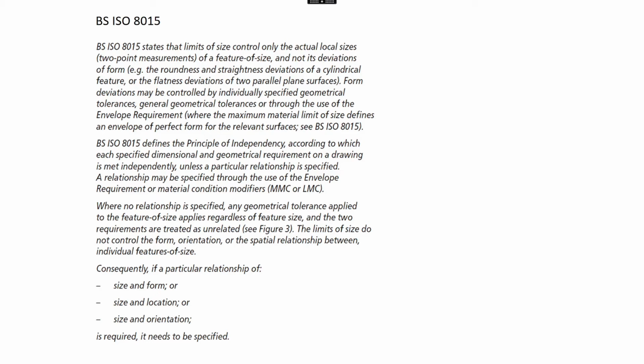So this is actually used now more instead of the triangle with the I in it. So you say it's drawn in accordance with BS 8888 and toleranced in accordance with ISO 8015. So that does the system of independency. So it must be clear when you're doing a drawing which system you're using, or which system your company standards are based on. It has to be based on one or the other really, for people to understand what you're actually trying to do.